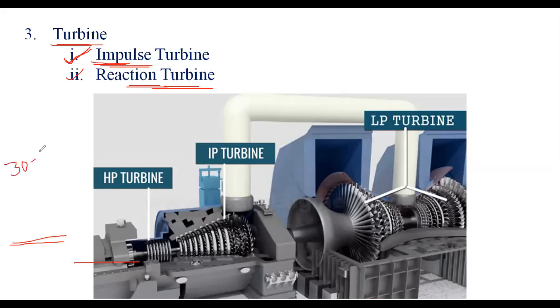That is in the low pressure turbine. For example, in the low pressure stage the turbine rotates at either 1180, 1200 or 1220 rpm. In the intermediate pressure stage it rotates at either 1320 or 1380 rpm. The high pressure turbine rotates at 1500 rpm.